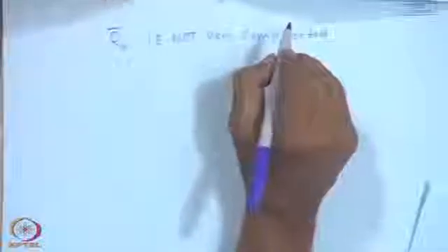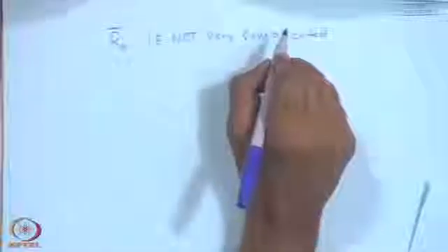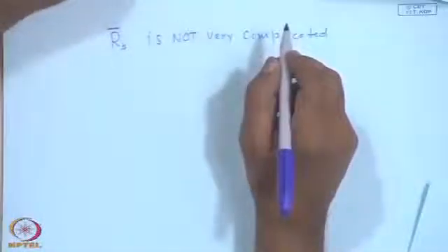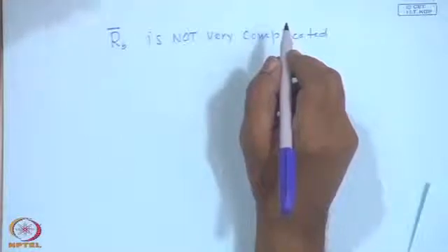Surprisingly, it looks like you are integrating the numerator of R B and the denominator of R B separately, that is, integral of I B cos theta by integral of I B cos theta z to get R B bar. That is not a mathematically correct argument, and it so turned out that the cos theta z term gets cancelled and hence you have this result.